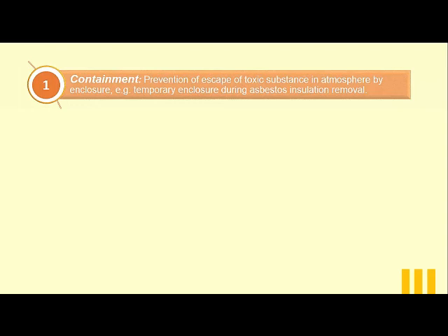For the purpose of containment, 2 main methods can be used. The first is dust collection systems. These are designed to handle heavy dust loads. And the second are the scrubber systems. These are a diverse group of air pollution control devices that can be used to remove particulates and gases from industrial exhaust streams. Some examples of scrubber systems are spray scrubbers, Venturi scrubbers, mechanically aided scrubbers, and wet scrubbers.